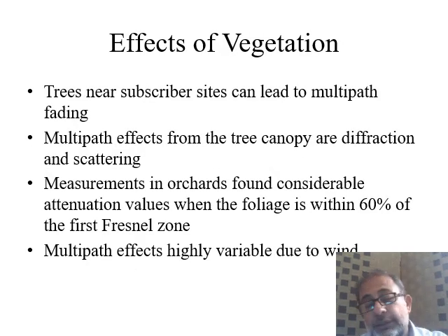There is also a great effect of vegetation on our communication over line of sight. As we have already seen and calculated the Fresnel zone, what we need to do is to avoid any obstruction within the 60% of the Fresnel zone.